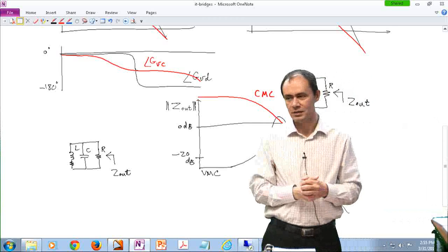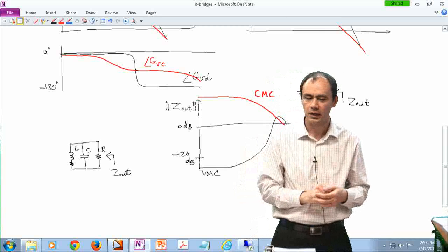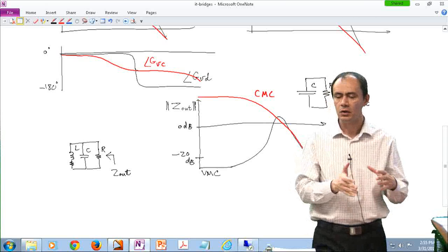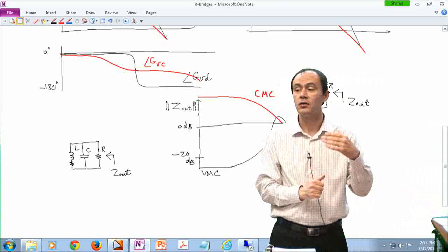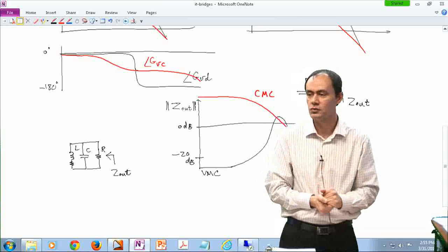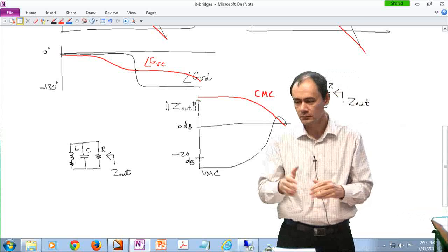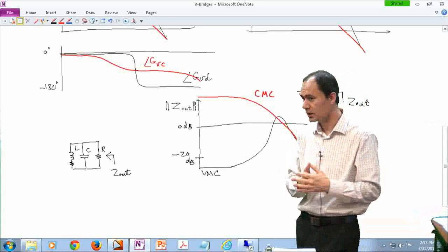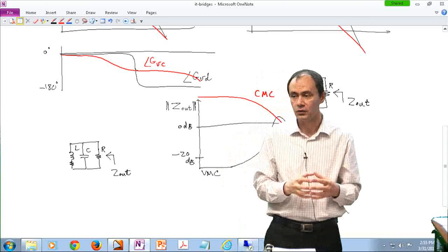Then when you are in a standby situation, your CPU is not processing much power, and then your current maybe is only 2 amps. Now, your converter is your priority because you want to operate your converter at higher voltages because it's more efficient. So instead of providing like 1 or 2 volts to the output for your CPU, you give it 4 volts this time, because the CPU can handle those losses even though your voltage is larger. So there are applications where you want to have good control on the value of your output voltage.